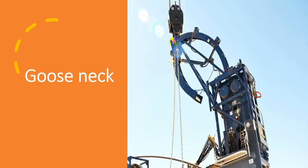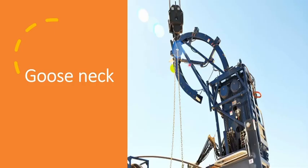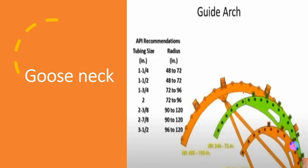This is the shape of the roller for different sizes of coil tube. This is the gooseneck in retracted position. If you want to expand it, you push hydraulic oil into this piston from the cabin or wherever. It pushes this part, so it is erected like this. The radius of curvature of the gooseneck is determined by API recommendations. So for a given tubing size, we have a range of gooseneck radius, as you can see from this slide.